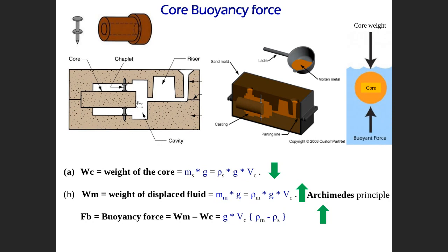As I told you before, a core is complicated. If you can avoid having a core in a mold, it will be better, because you see that it's really complicated. But in some cases, it is essential to have a core inside. If the dimension is very big and you don't have a core, then you have to do machining, cutting this out, which is a big waste of material. In this case, the core is essential. You must consider the core inside the mold.